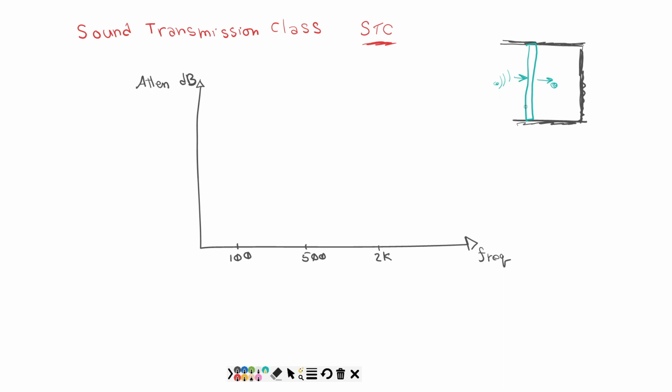Transmitted through. Now, since I know there's going to be no flanking sound because of the way I've built this, and there's no structure-borne sound if I do this correctly, the only sound energy that gets through is from this test material, right? This test barrier. So I can figure out just how much of a loss there is because I can measure what the SPL is over on this side, and then I measure the SPL on this side. I can figure this all out, right?